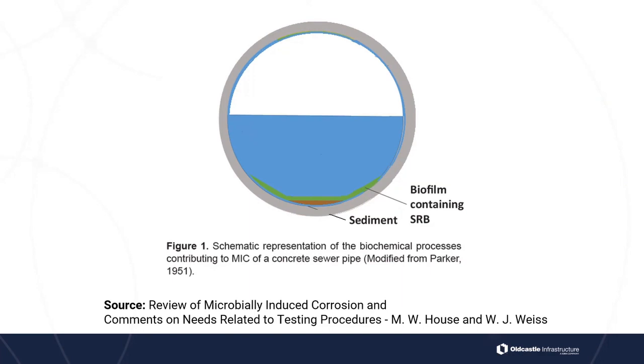So, we're talking 3 sheets of paper to a little less than the thickness of a dime. All right. So, depending on the velocity and flow and the frequency of abrasion by solids in the waste stream, this biofilm can vary in thickness. If you have a lot of abrasive materials going through your sewer, it might reduce the size of this biofilm. Now, unlike the conditions in actively flowing sewer pipes, the lack of significant fluid shear and physical abrasion under slow-moving or settled water situations like you'd see in maybe a septic tank or a slow, very flat sewer pipe where the water isn't flowing very fast, you may see a thicker biofilm in those surfaces below the water line.